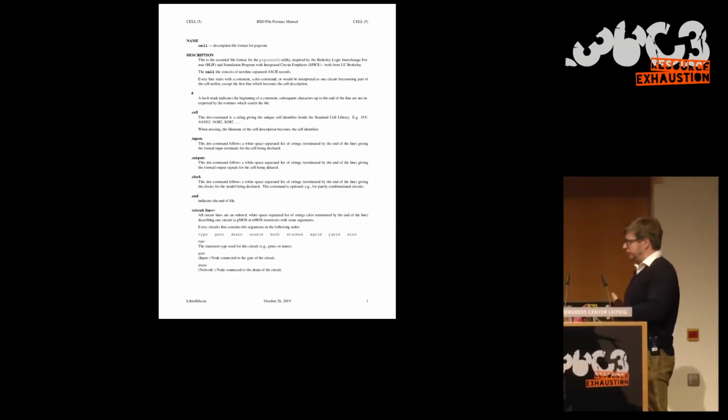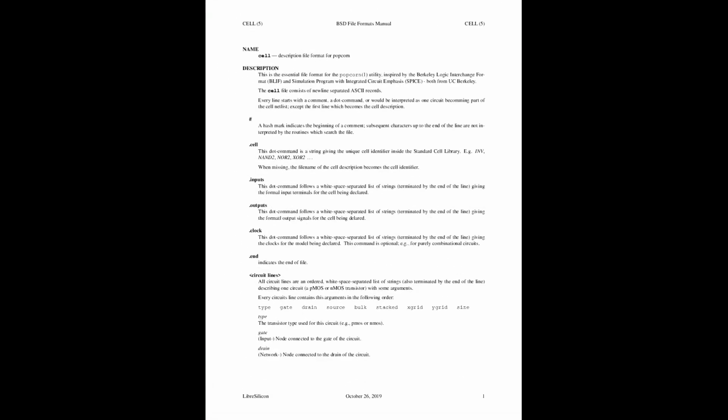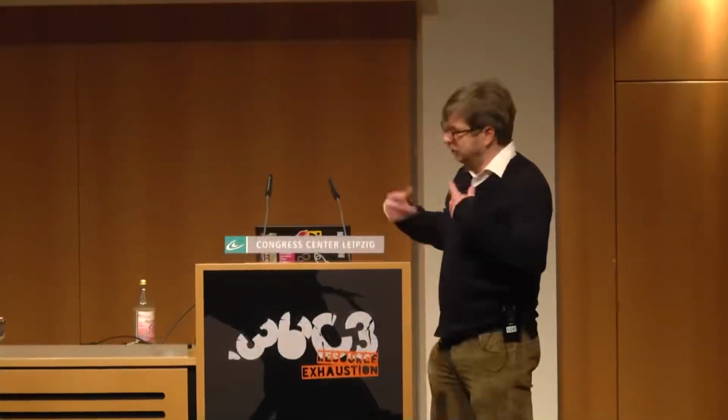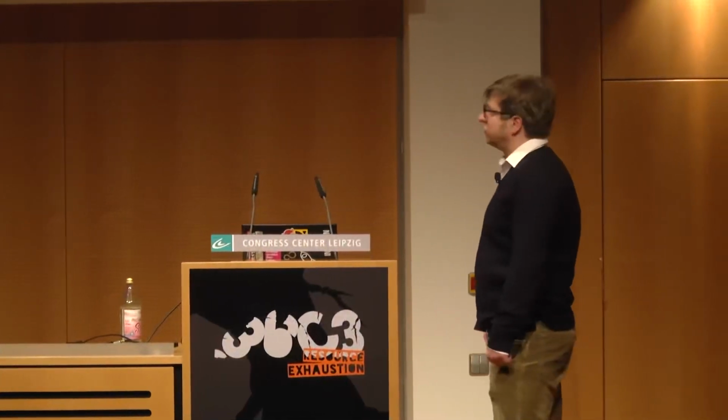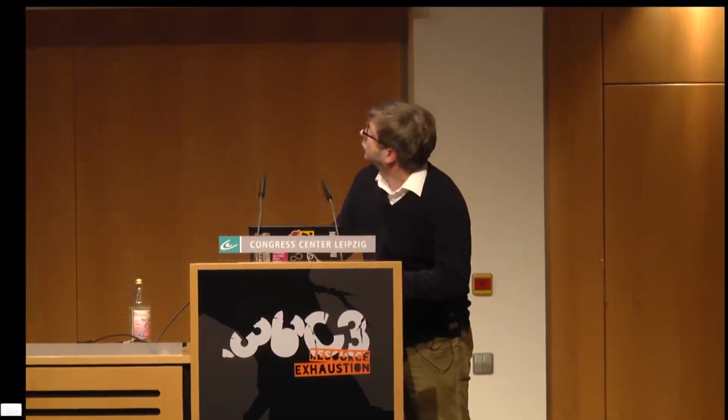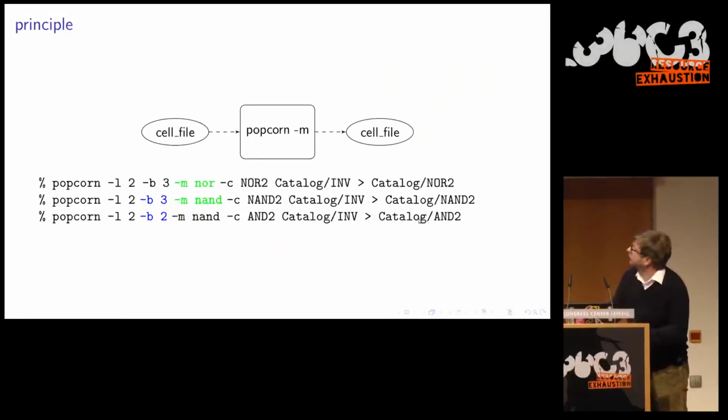There is a method to do the right dimensioning, called logical effort, and it optimizes between energy usage and size of the cells. It's not done on the fly, but when the cell is created, it computes the value needed.